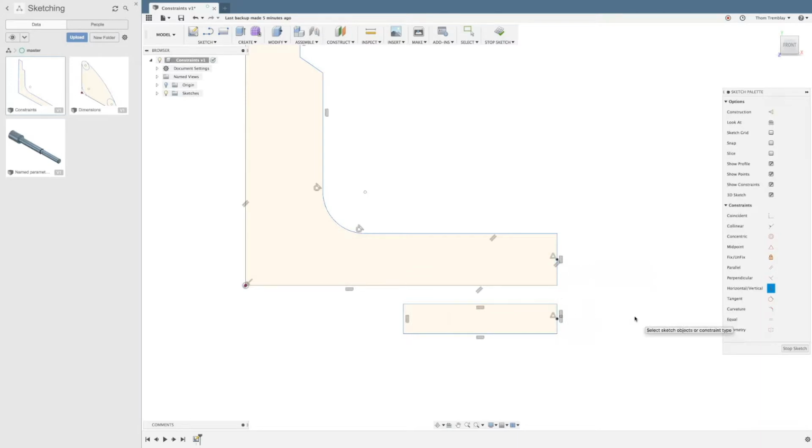And here, because of the proximity, it created a vertical relationship. So there are times where you're roughing in a sketch and you go to center something on another object and you get the perpendicular or wrong behavior. This is probably what's going on, is you were just a little too close to another option.